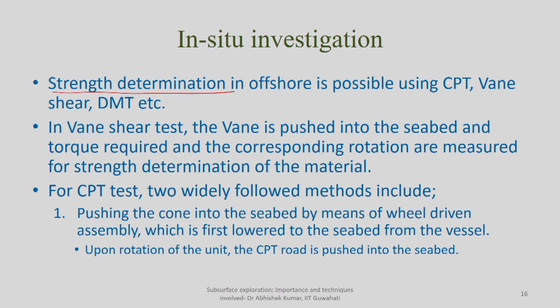So, the primary objective for deep geotechnical investigation is strength determination in the offshore environment, particularly the seabed material or the material which is below the seabed, by means of CPT test, vane shear test, or dilatometer test. In the last couple of decades, DMT has also been proven very accurate in terms of strength determination for the offshore environment. So, in vane shear test, the vane is pushed, again the more general practice is lowering the assembly onto the seabed, and from there onward you can do the test.